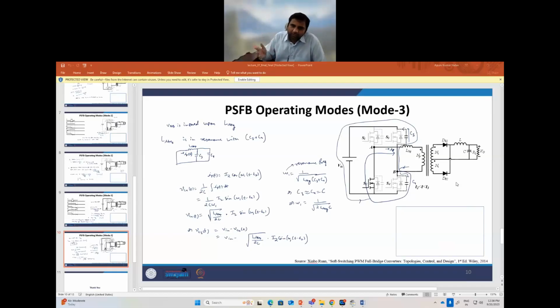So it is a good amount of current, because generally you keep the ripple within 10%. You can say 1 volt peak to peak, or 1 ampere peak to peak. One ampere peak to peak means it is a very small ripple component. What is the ripple current? I kept a ripple voltage, but I have not kept the ripple current.